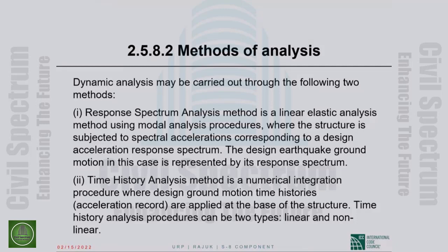Okay. Entire chapter 16 of ASCE 7 is devoted to nonlinear time history analysis. That is not our topic today. We will concentrate on modal response spectrum analysis, and when dynamic analysis is required, the vast majority of engineers would still do modal response spectrum analysis. And that's definitely true outside of the US.